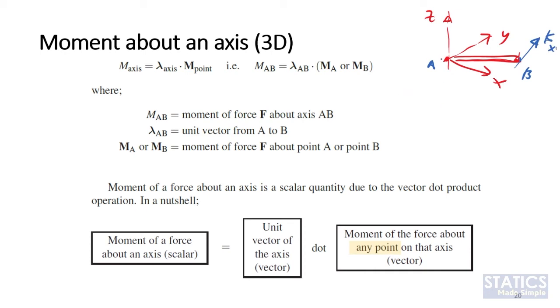We can get moment about A, which is equal to force times the perpendicular distance from the point of moments towards the line of force. Let's say this is the perpendicular distance, D. So in 2D form, we know that moment at A is equal to D times this force. What we don't tell you is that what we are calculating here is actually a moment about an axis. And that axis is out of this xy plane, along the z-axis. So that's what you are getting here.